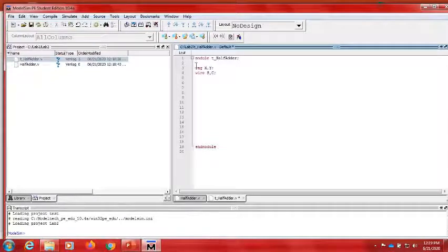What we are doing here is, define your input connection of the module as type reg, and define wire, or you can say define the output of your module under test as wire connections.